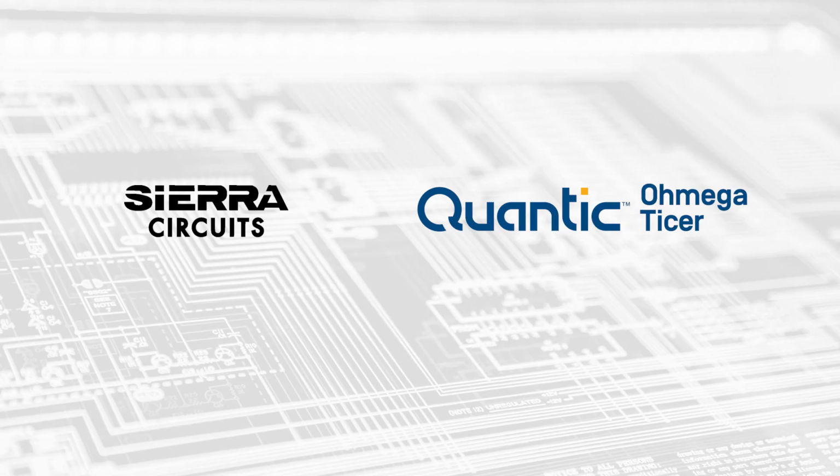We have done some RF characterization in the embedded resistors, and we do have some things available. Like I said, the attenuator was tested up to 60 gigahertz, and we've had very good results with that. We also tested the effect of the resistor material being under the traces up to like 40 to 50 gigahertz, and there's a minor impact of loss by having that resistor material underneath it.